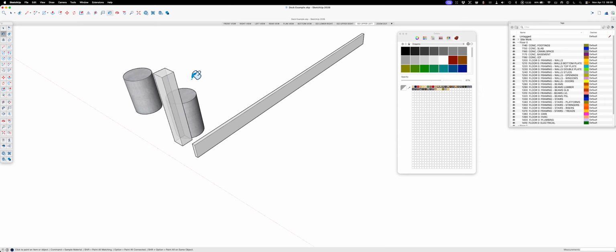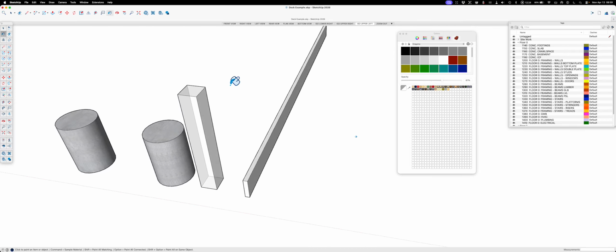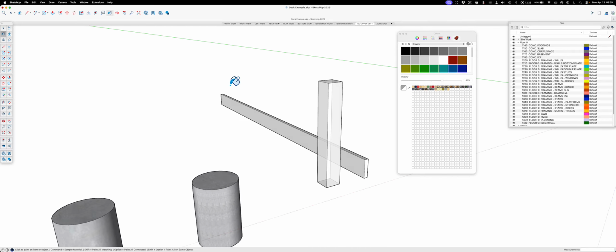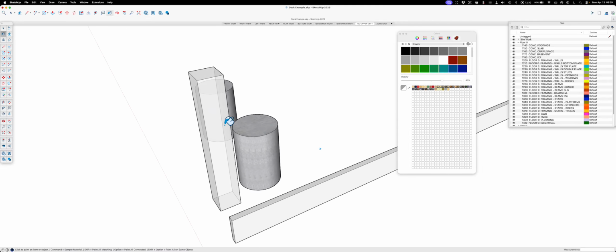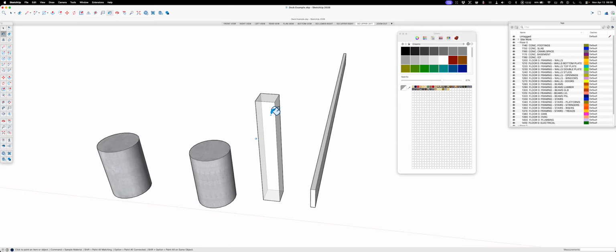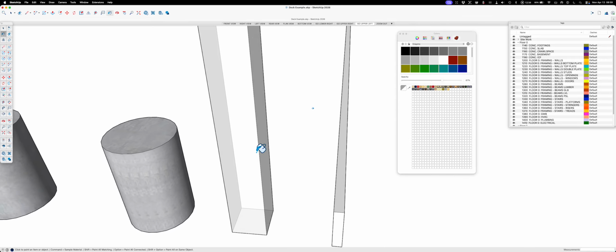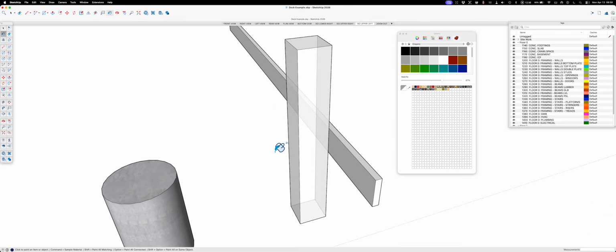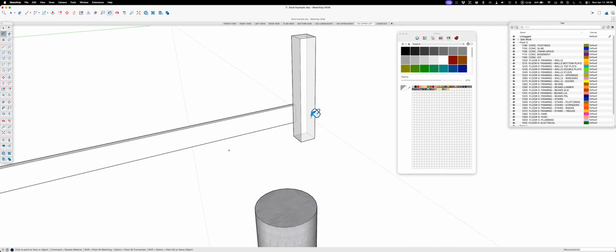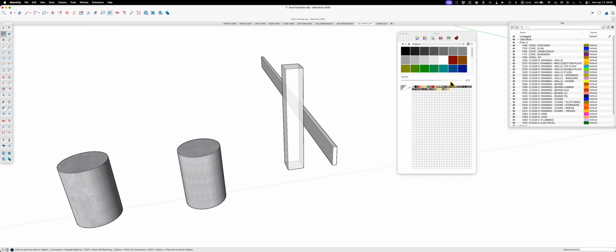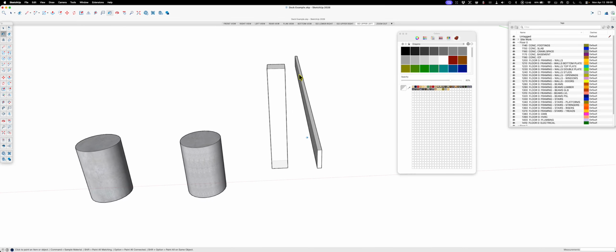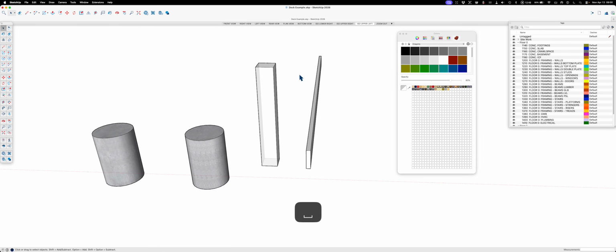But now, as you look, I'm going to use the 3D mouse here so that you can see through that. So there's going to come some instances where when you build, you're going to want to have this post here, but you might want to see if there's a connector on the backside. You might want to be able to see that from different angles rather than just coming all the way around to see it. So that's a personal call. I'm going to make that not quite as opaque or opacy, whatever.